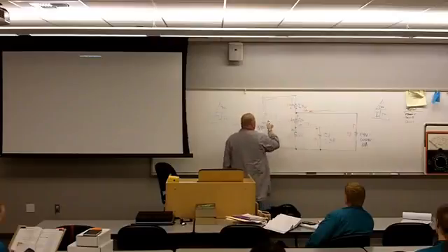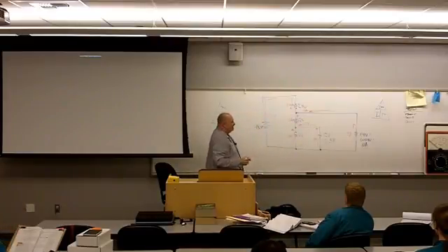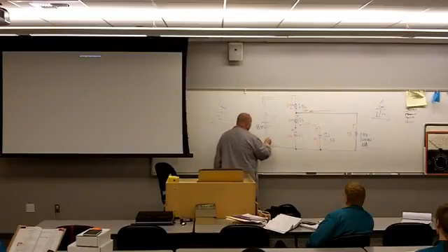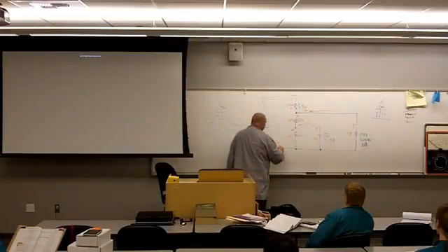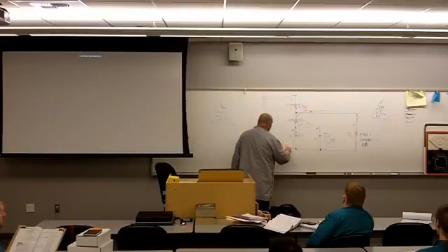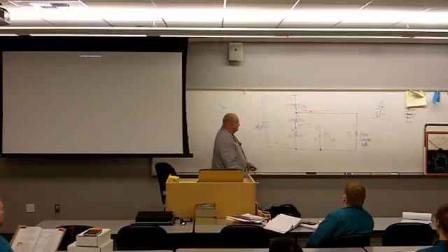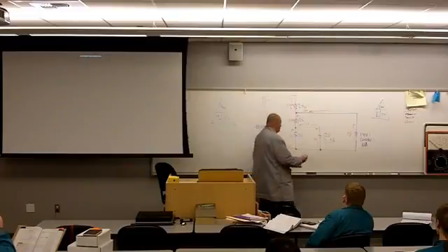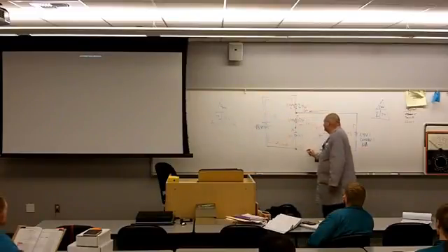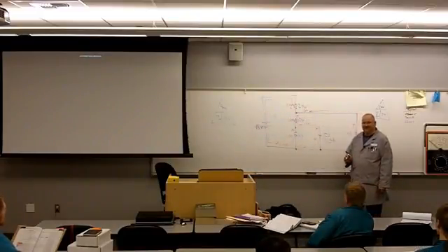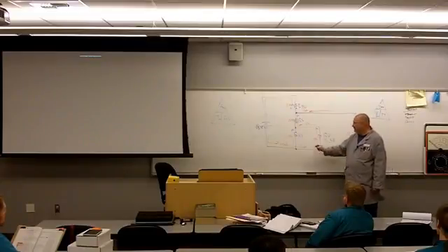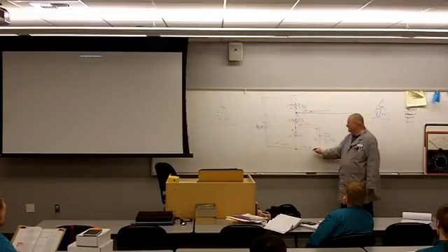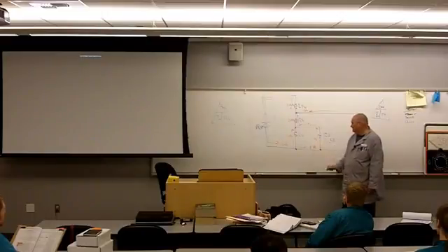So we know that we have 11.55 amps coming up through here. Boom. If I've got 11.55 amps flowing into my power supply, how many amps must I have flowing out of my power supply? The same. Okay? So that means I've got 11.55 amps flowing into this node. If I've got 11.55 amps flowing into this node and 1.05 amps flowing out of this node, how much current do I have flowing in this direction? 10.5 amps. Do you agree with that?